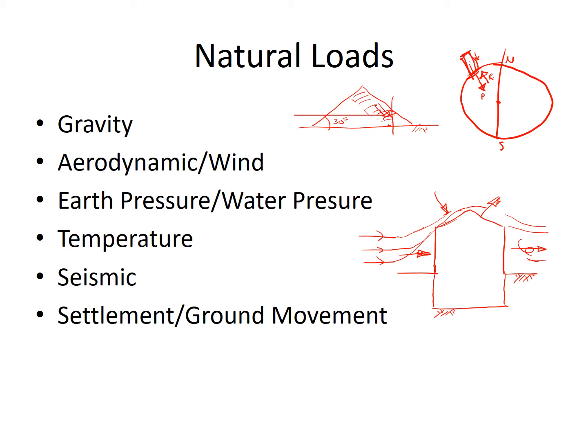So we will get forces at this point and this point due to earth pressures. So again, we will have to design this building for these earth pressures. Now, we might also have a water table, subterranean water table at this level here.